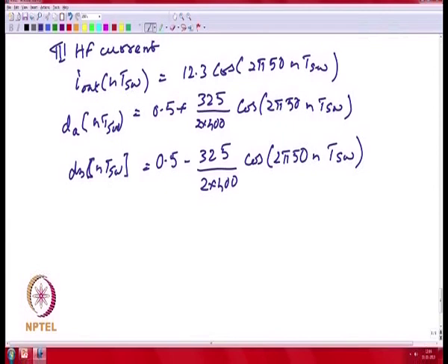That current now would be 2 pulses per TSW. So you are having your DC bus current also now at 20 kilohertz and its sidebands and harmonics. So, based on the expression that we had just written previously, you could calculate your ICDC at 20 kilohertz is 3.83 amps.